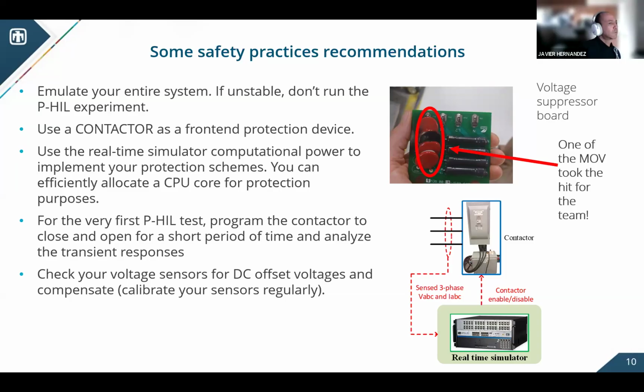And we go for the basics: overcurrent, under voltages, but you have the opportunity to be creative on how you protect your device here. If you don't have enough computational power, or you have all the cores allocated for more elaborate simulated systems, well, I've seen people using SEL devices. Just an overcurrent device will do the work. Just make sure that this contactor is your first layer of protection.